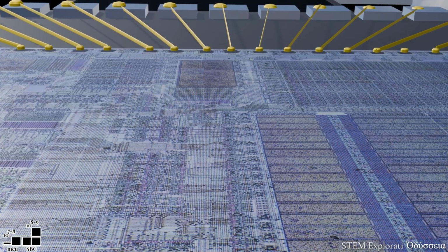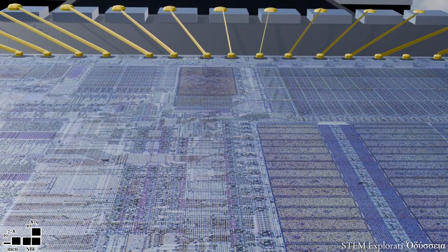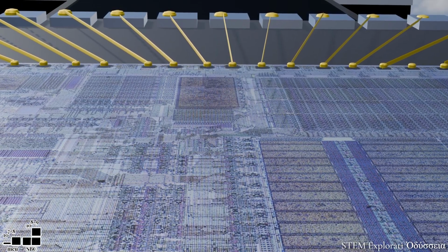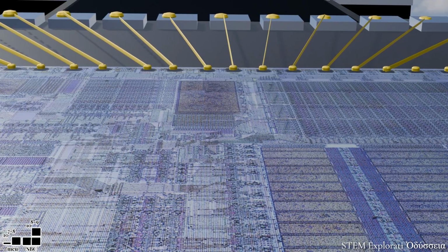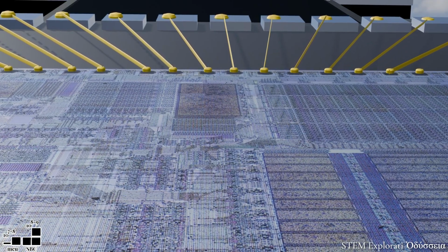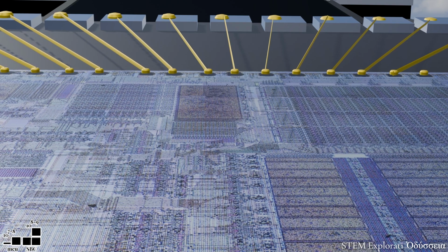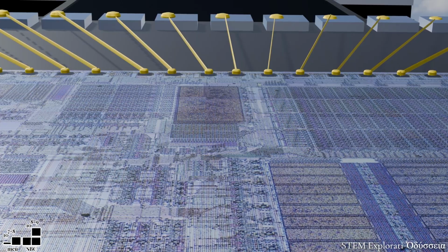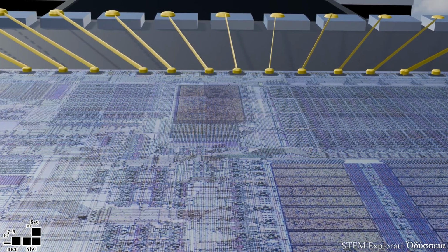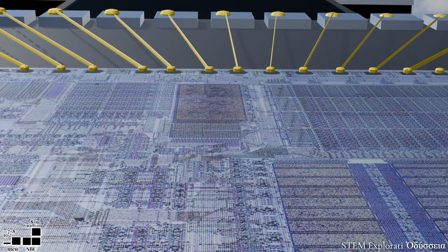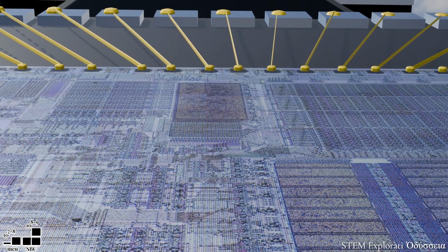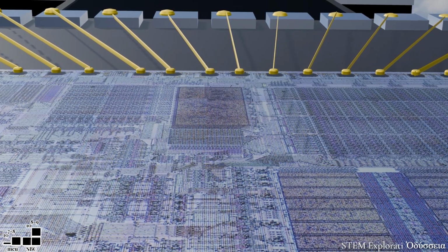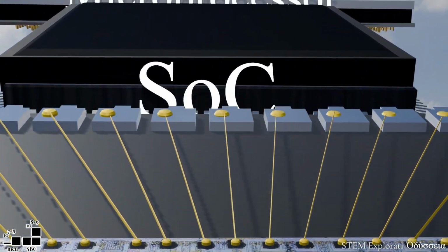Even the classic PIC-16 series, which became popular in everything from toys to appliances, typically had just tens of thousands of transistors. Modern industrial versions of the 8051, still in production today, have been refined with better manufacturing. But they're still simple chips with transistor counts in the tens to low hundreds of thousands. Even high-end 32-bit microcontrollers, like ARM Cortex-M7 or PIC-32s, only pack in a few million transistors. And then we step into the world of SoCs.